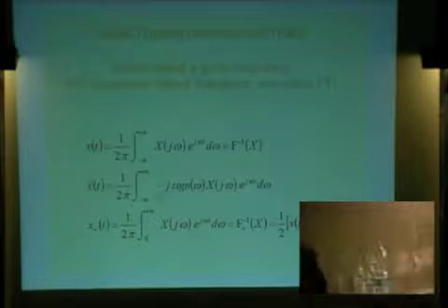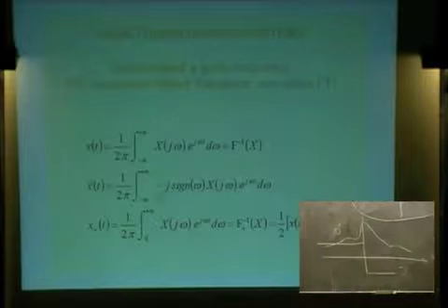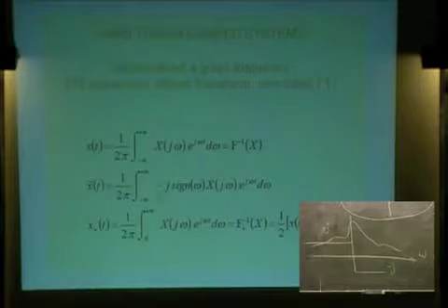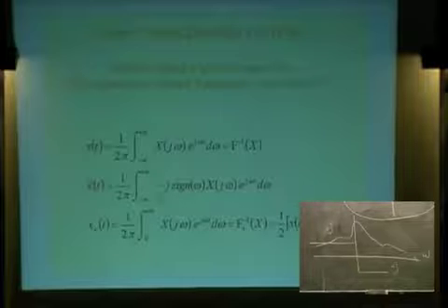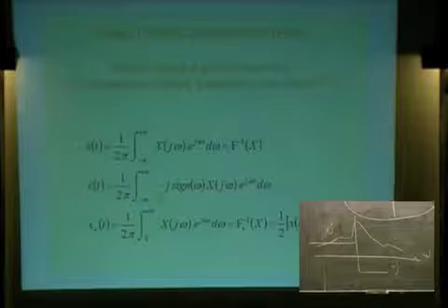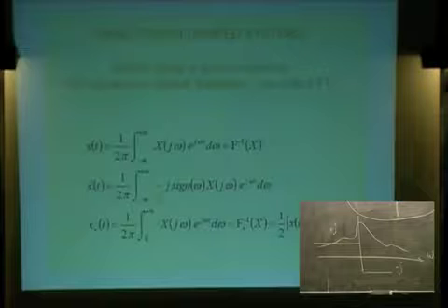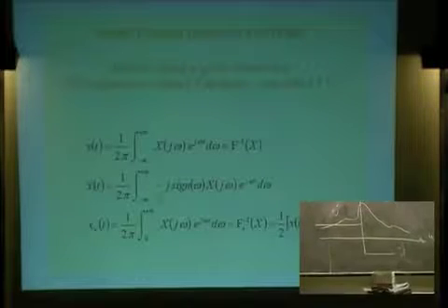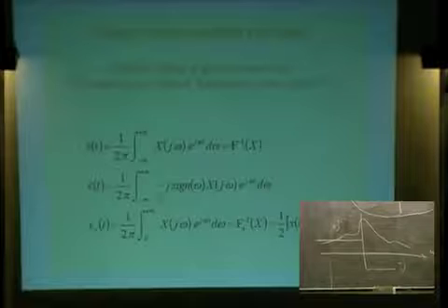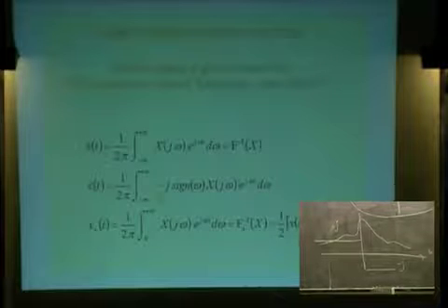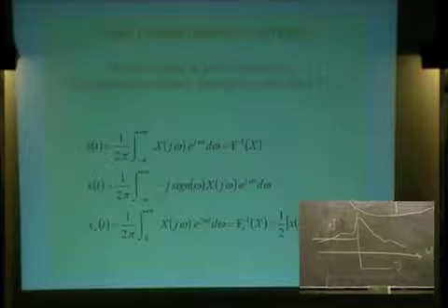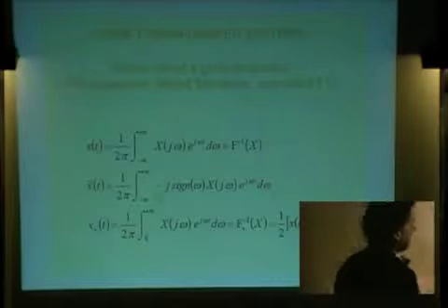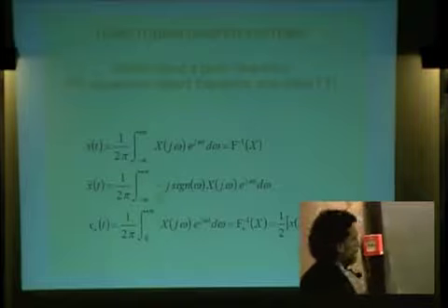It's easy. So I can take, for example, MATLAB, I perform the Fourier transform, then I take the file with the Fourier transform, I multiply the positive frequency part by minus j, and the negative part is multiplied by plus j. Then I take this signal and convert it back to the time domain. This is the Hilbert transform of the signal. What is the meaning?